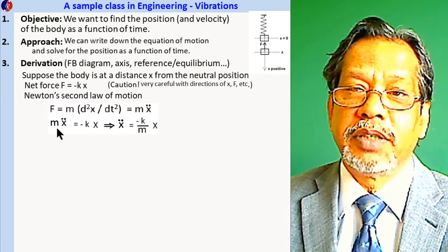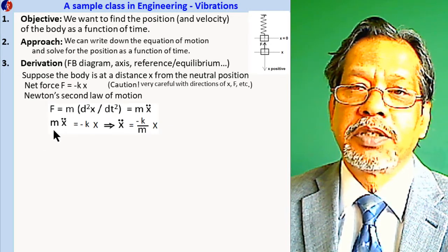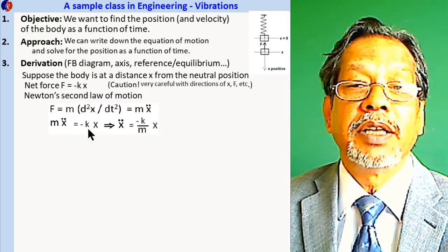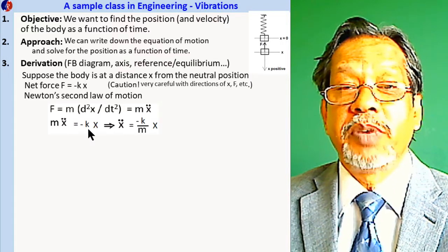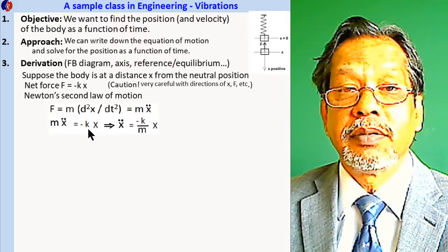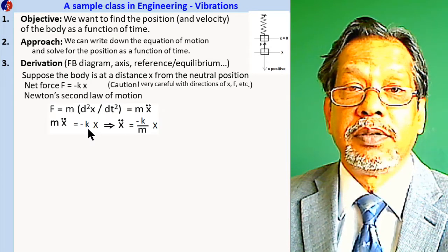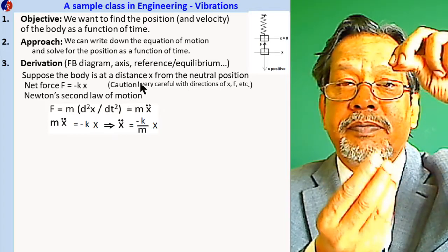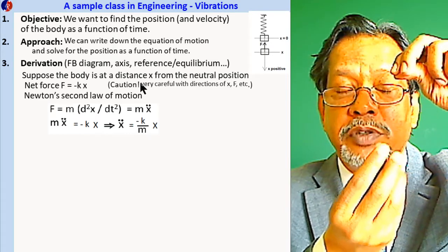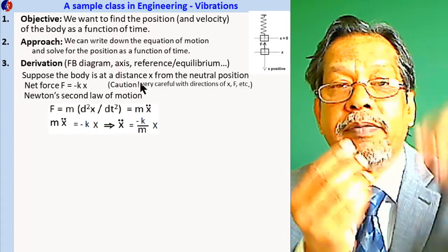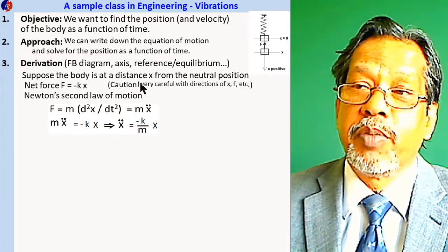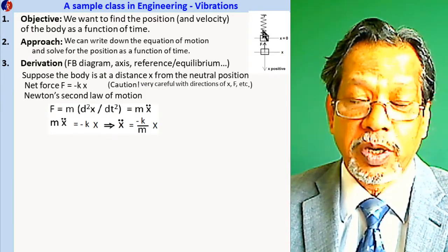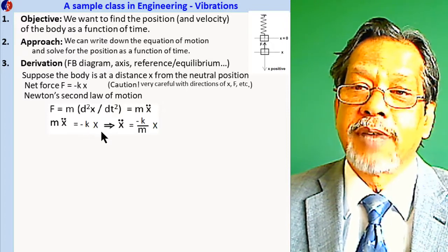So we just flip it and say mass times acceleration equals force, and the force I have seen is the spring force here, minus kx. k is the spring constant, which is the spring force caused by unit displacement. If you pull the spring, you measure the force, you measure the displacement, force divided by displacement. That's per unit displacement, how much force is caused. And we are assuming this is a linear spring. All right, so this formula is valid.